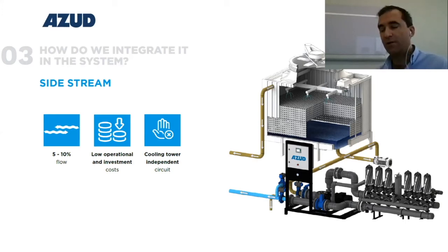Also, very important, you have a lower maintenance cost. Traditionally, cooling towers are cleaned by draining the tower and having the sediment removed either mechanically or manually from the sump. The costs associated with this cleaning process include downtime, labor, loss of water, and additional chemicals. So cooling systems that are clean with a side stream filtration routinely provide longer periods of continuous operation before being taken offline for required maintenance.